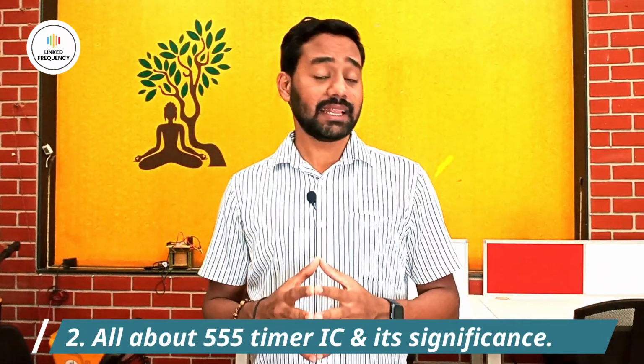Now let's talk about the LM555 timer IC and its significance. LM555 timer IC is a digital electronic integrated circuit, which is used for generating time pulses in digital electronics. This is widely used for sequencing and switching applications where a time-dependent design is required. It is a linear monolithic integrated circuit with an 8-pin structure, available in SMD and THD packages. It requires only 2 external resistors and 1 electrolytic capacitor to tune its turn on and turn off time, or you can say the width of the pulse and the space of the pulse at the output side.